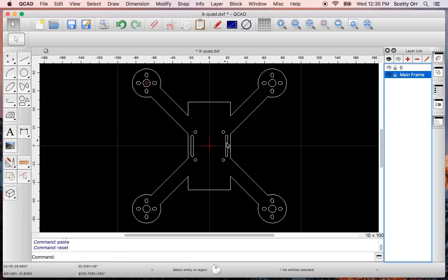However, there are some rough things that a CNC cutter would have trouble with, like all of these sharp angles and right angles. The CNC cutters are going to be using a round cutting bit, and so you can't really do corners. And when you have sharp corners like this, it is a fracture point where in an accident, that would be an easy place for it to break. So what I like to do is produce smooth corners.